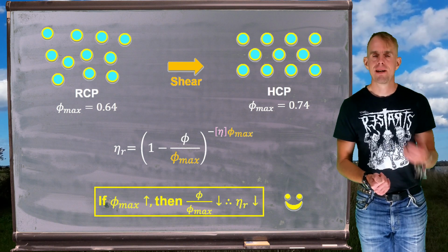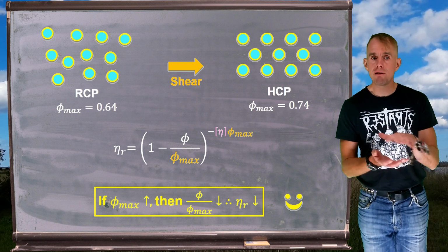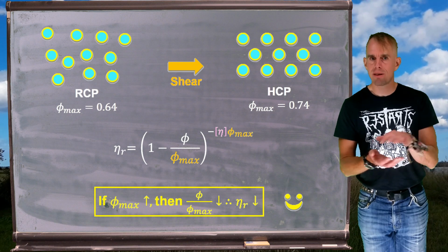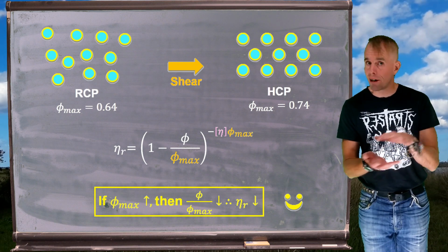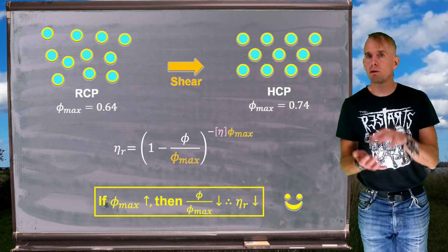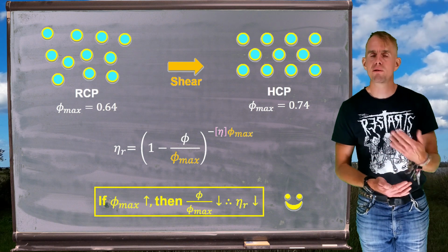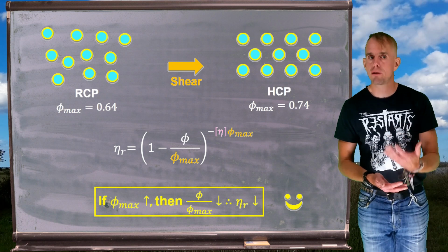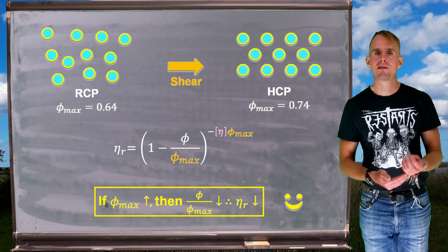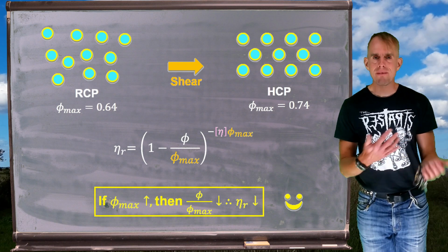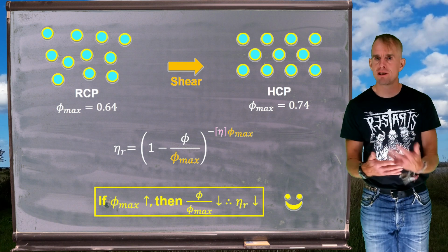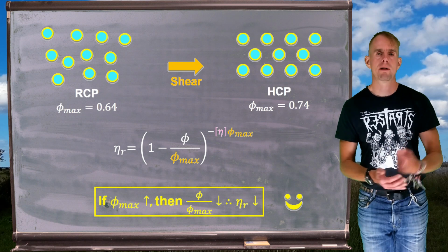systems. Now, if we imagine Brownian forces, then introduce disorder into that system, over time we can see a viscosity recovery. And if you remember what we were talking about in the lecture on thixotropy, then we can see that this competition between Brownian disordering and shear ordering not only describes shear thinning, but actually a thixotropic response as well.